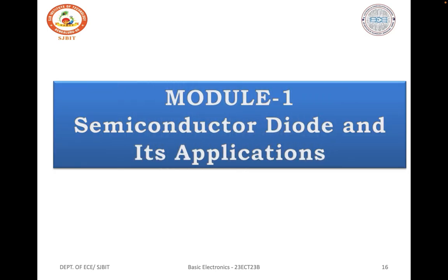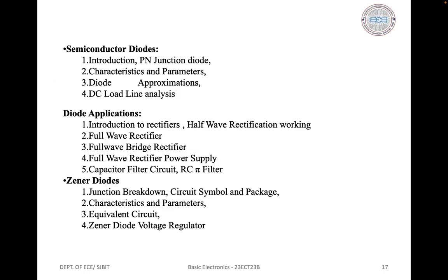Here we are discussing module 1, semiconductor diode and its applications. In this session we will discuss diode applications like what is a rectifier and the different types of rectifiers like half wave rectifier, full wave rectifier, center tapped rectifier and a bridge rectifier, full wave rectifier power supply, capacitor filter circuit, RC pi filter, all these things.